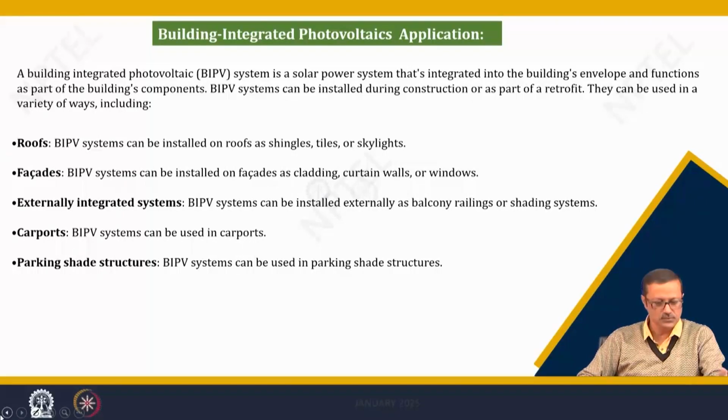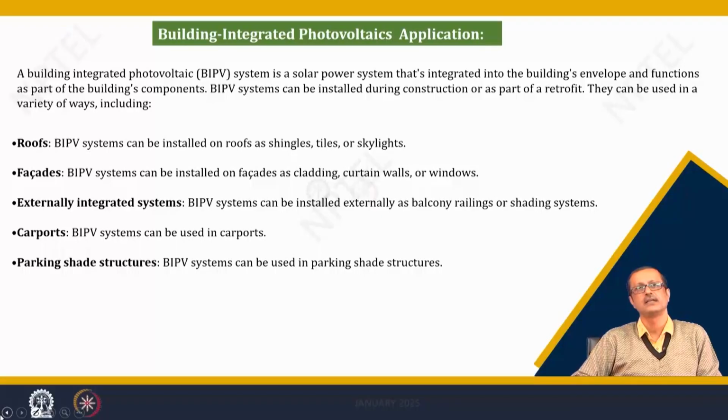So, if I choose only those areas, not the actual longer or wider facade area, that also can be incremental as I increase the height of the building, and can fetch some electricity. Why can we go for these externally integrated building systems? Sometimes an architect may not like to wrap the whole building with the blackish building integrated photovoltaic. It may not look fitted for that particular area aesthetically or maybe culturally, and may not be viable. In those cases we can go for those small areas and still generate some electricity.